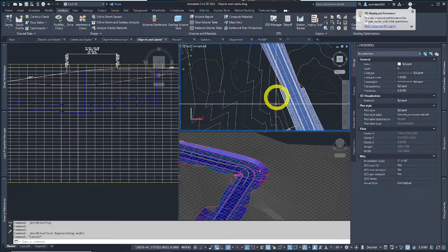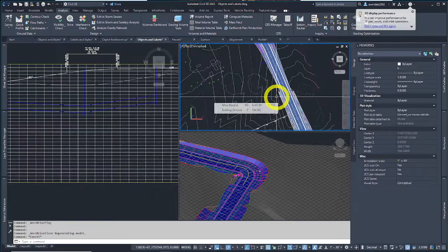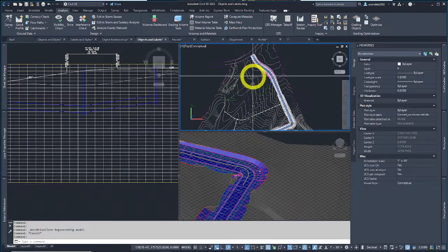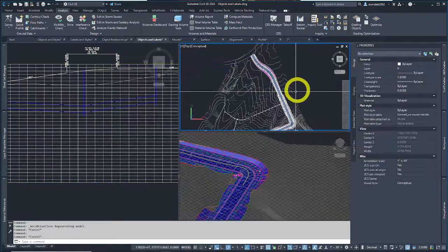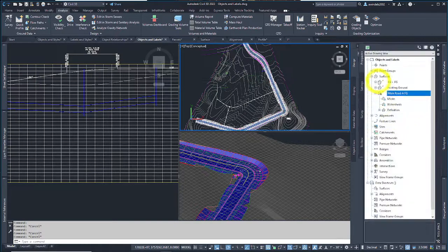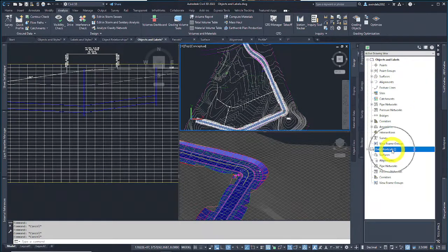So one thing with those big commands, just give it time to chug in between. Don't shock it. Civil 3D, it likes to crash enough on its own. So we'll move into the last area of sharing data in a dynamic environment, which mostly involves us learning a little bit about data shortcuts, ways to dynamically link Civil 3D objects between drawings so multiple users can work on designs at the same time is one of their main goals.